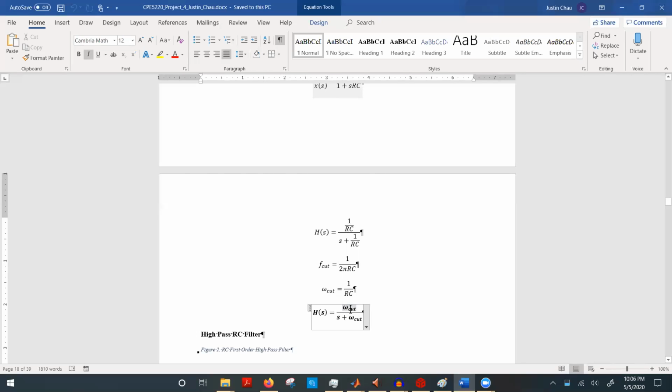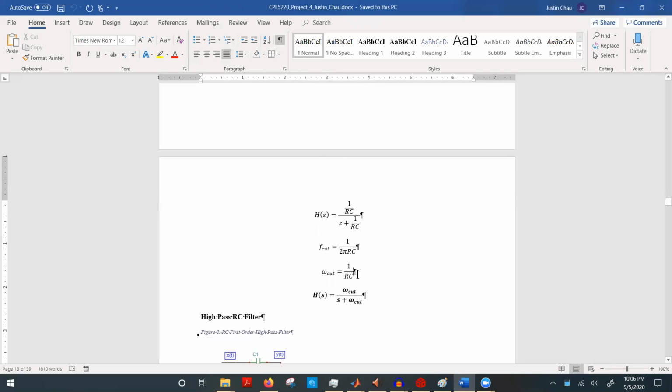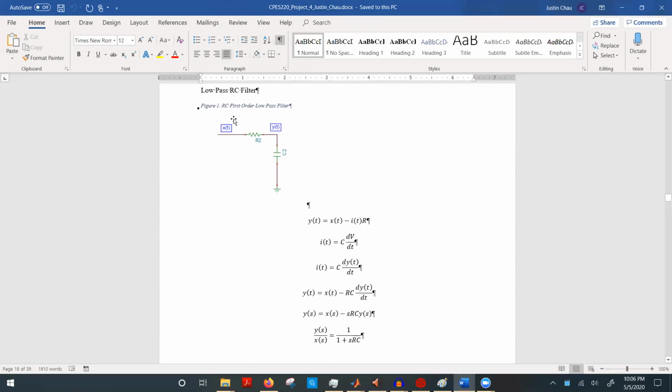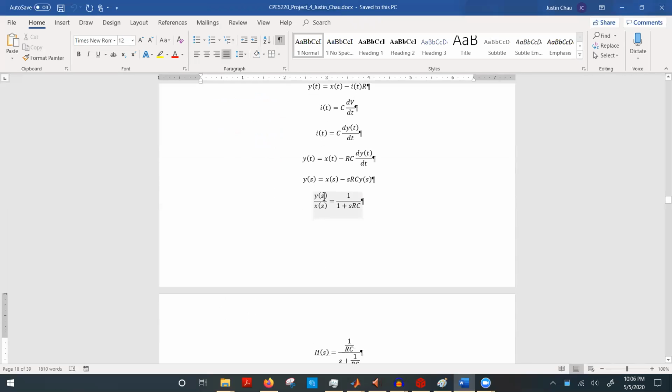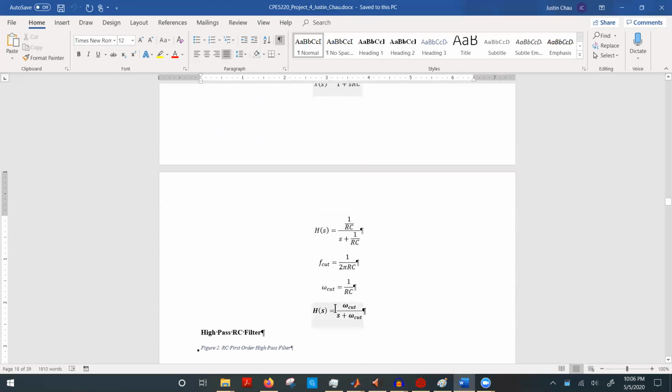This can help simplify our equation. What this is really saying is that I don't actually need to specifically design a resistance and a capacitance in mind. Since I'm designing a filter, I'm instead just going to design based on what I want my cutoff frequency to be, and not worry about the specific values of resistance and capacitance in my design.